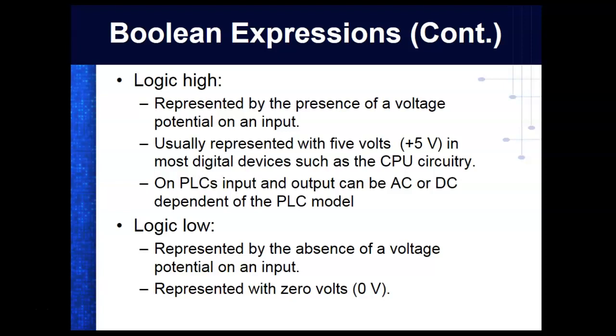Some PLCs deal with 5 volts, but almost all your PLCs now are looking at 24 volts. So that's a pretty standard power supply. This guy right here, that's what we're using: 24 volts, not only on the input, but also the output. That's why I'm not sure to put my hands up here, so I can't use the connection.